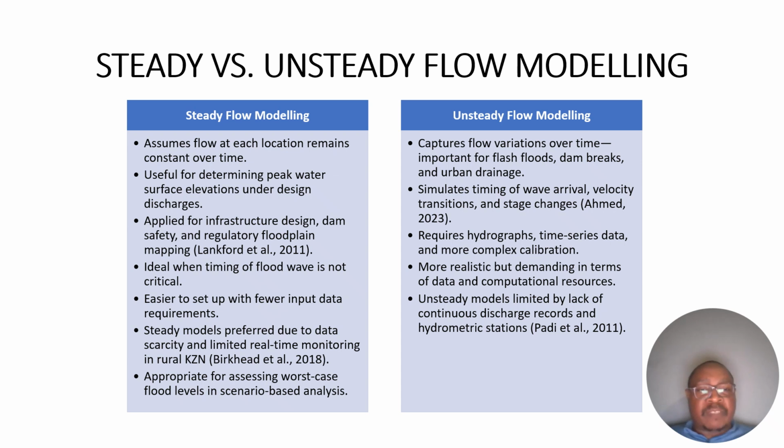And then thirdly, it applies to infrastructure design, that is dam safety and regulation of floodplains. It is ideal when the timing of the flood wave is not critical. It's easy to set up with fewer inputs and data requirements, and the steady model is preferred due to data scarcity and limited real-time monitoring. And lastly, it is appropriate for assessing worst-case flood levels in scenario-based analysis.